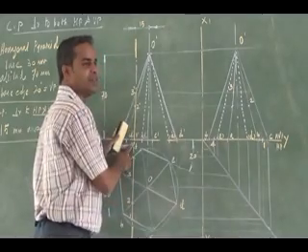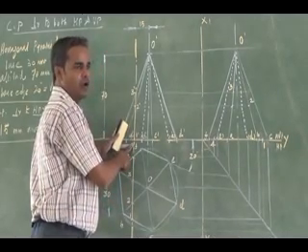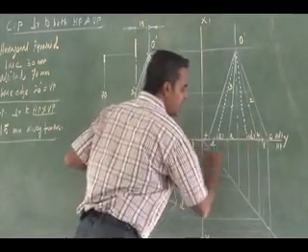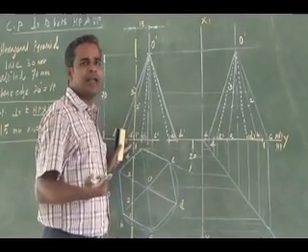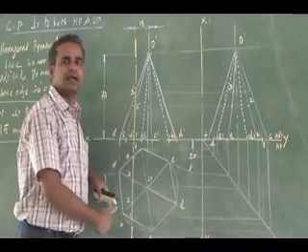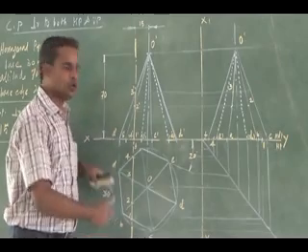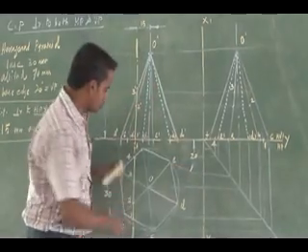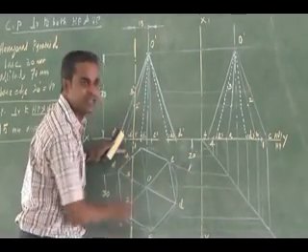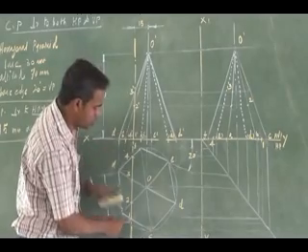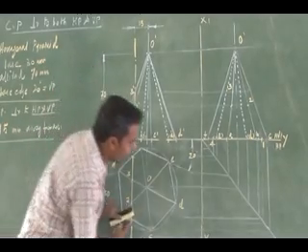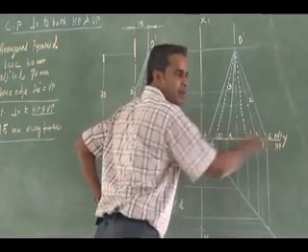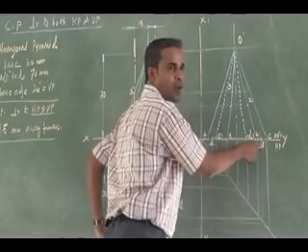Coming to the base cutting points 1 and 4, they are on the same reference line, so I cannot project them horizontally. Where exactly they will fall, I don't know. So I can get it from my top view. The top view details are linked to the side view with a 45-degree line, you know. These cutting points 1 and 4 in the top view are base cutting points. I project cutting point 1 to the 45-degree line, then to the base in my side view. So exactly I am getting it here, 1.